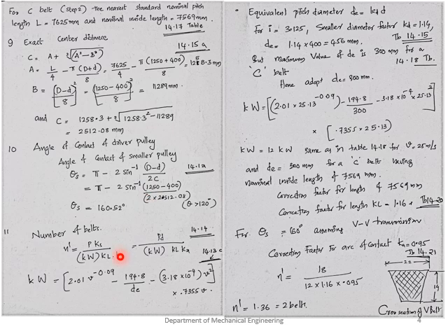So everything is known in this equation for the kilowatt rating. Substitute those values and find the kilowatt rating. It is equal to 12 kilowatt. You will obtain this value as 12 kilowatt, and this is approximately the same as in table 14.18 for V equal to 25 meter per second and D equal to 400 mm for a C belt having a nominal inside length of 7569 mm.